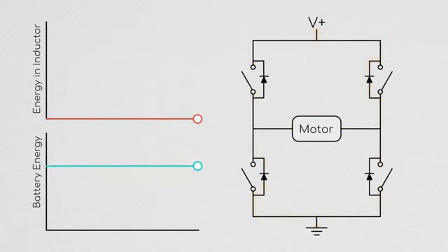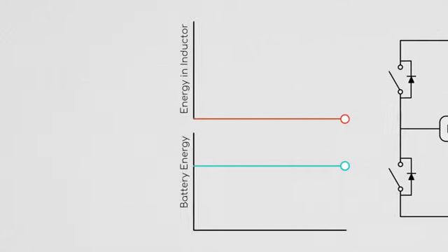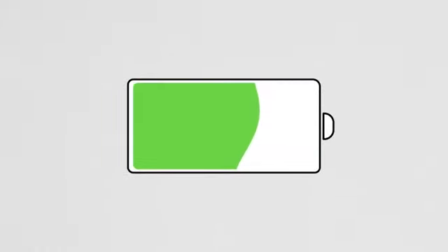Because this energy gets drained out of your system during each unforced phase, you will then have to run at a higher duty cycle than you otherwise would to maintain the same level of current, and regeneration isn't perfectly efficient. So you end up spending more energy during the extended forced phases and getting back an amount of energy during the unforced phases which is less than the extra you spent during those forced phases. But the net increase in energy expenditure isn't the only issue here.